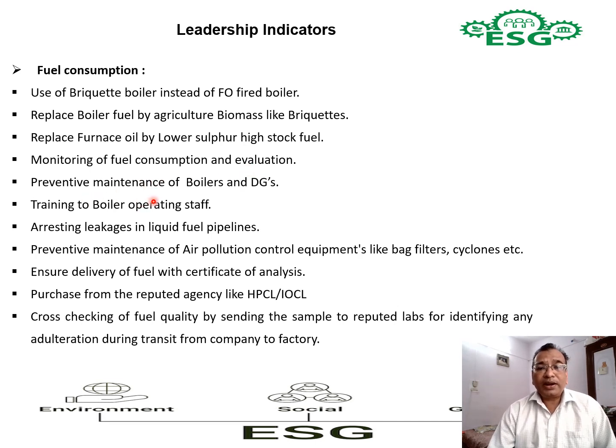Then preventive maintenance of the boilers and DGs. This is very important, because you have to maintain the efficiency of the boilers and DGs when they are in operation, as gradually the efficiency is reduced with the running of the boilers or the DGs. So to maintain the efficiency at a high level or the same level, you have to carry out preventive maintenance schedules.